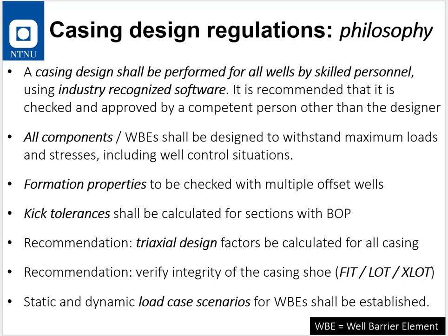Now, for sections before this, well control is very often tied to shallow gas or shallow water flow. These are things that come from understanding the formation properties. You will get input from the subsurface department, and you will make your design such that you're able to handle a flow even without a BOP. That's typically done with a diverter, so you're leading the pressure out of harm's way into a secure area.